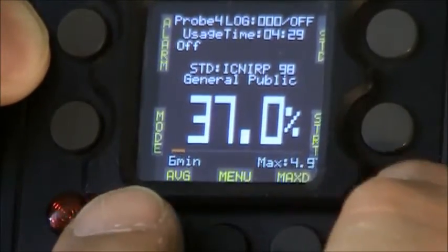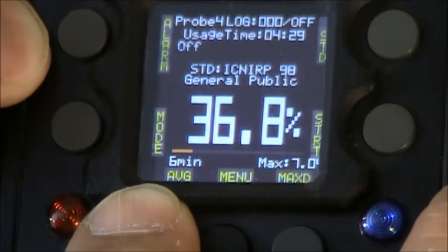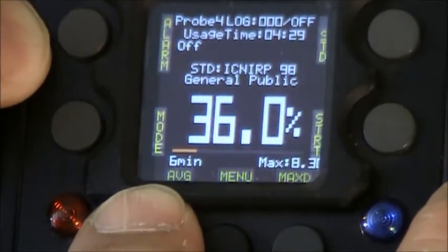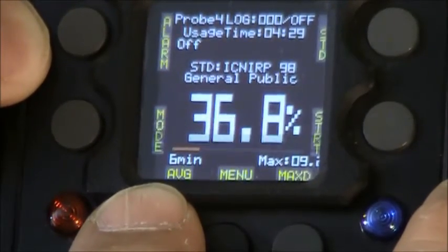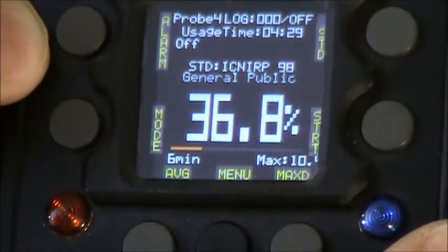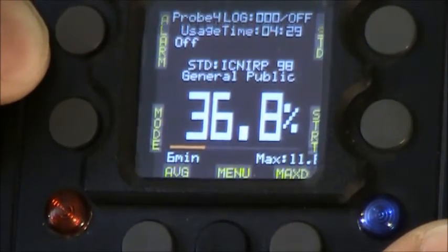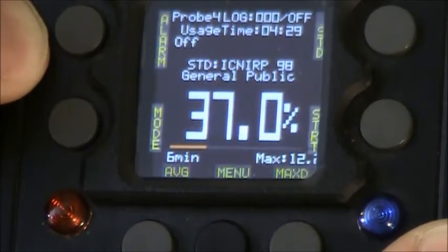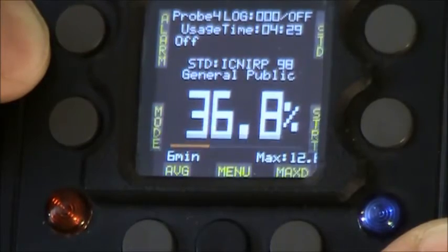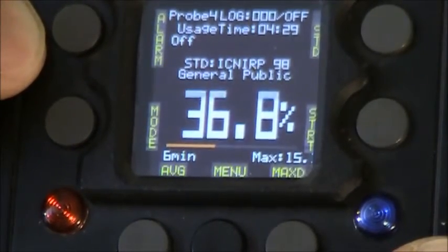The length of the red bar represents elapsed time, and when the averaging time gets to the selected averaging, like in this case 6 minutes, we will get a beep telling us that we achieved the averaging. We can take the reading. We can continue reading indefinitely, and the system will perform sliding average processing with the selected time.